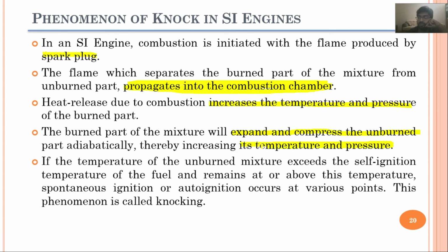And if this temperature and pressure goes beyond the self-ignition temperature, another flame will be produced in that unburned layer, and it will move against the main flame, and an audible sound would be produced, which is known as knocking. If the temperature of the unburned mixture exceeds the self-ignition temperature of the fuel, spontaneous ignition or auto ignition occurs at various points. This phenomenon is called knocking.